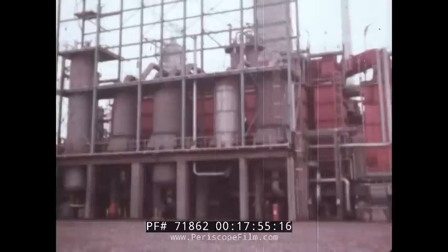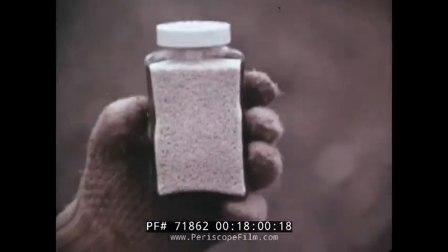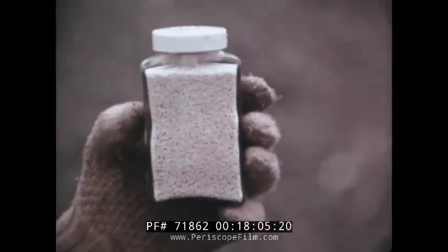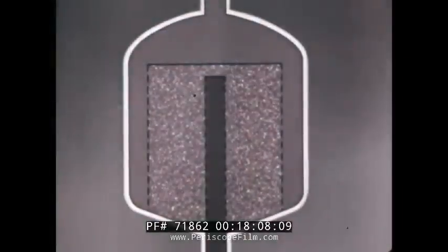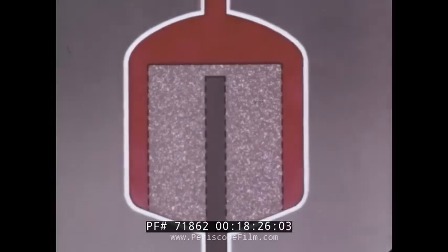A catalytic reformer uses platinum as the catalyst. A thin film of platinum is coated on pellets of aluminum oxide, and these are packed in the reactors. But reforming requires a lot of heat, and the process has to be done in 3 or more stages. The straight-run gasoline is heated to more than 900 degrees and fed into the first reactor as vapor. As it passes through the catalyst, reforming begins.